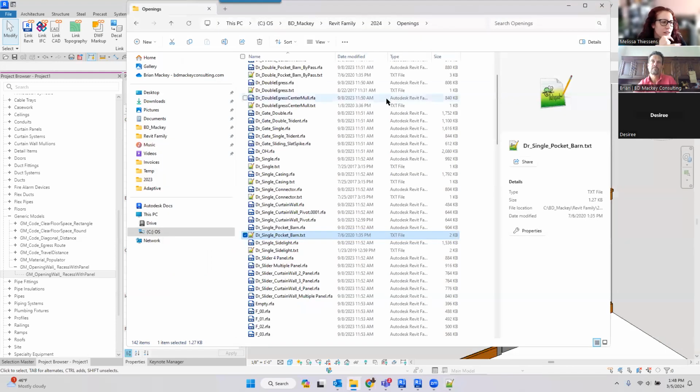So I was actually just thinking back to Ben's question. Instead of actually nesting in the structural angle, do you think you could just do it as a profile? You could just sweep your profile on there, but if you're looking like, hey, I want to see what my structural families are that I'm using in this project schedule-wise, you'd have to nest in a structural family. And again, the line-based ones don't really work that well. I've got it to work before, but it was a whole lot of hoopla and it broke in one of the upgrade versions. So now I'm just like, screw it. I have one where it's not 2-click. There's just a length value in there.